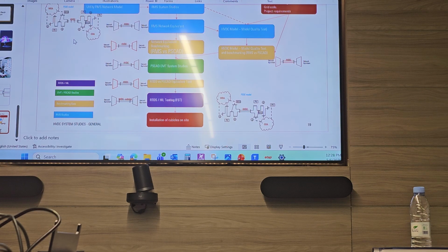So in some situations you will have a contract for this HVDC, but in parallel Saudi Electricity will have another contract to build some cable line, which you initially say, who needs this? It's not needed, because there are already two within this substation. Why do you need one more? Well, one more or additional investment may be required to keep your system stable in case of a fault, bus bar or fault on HVDC. So this is why this kind of testing is done here.